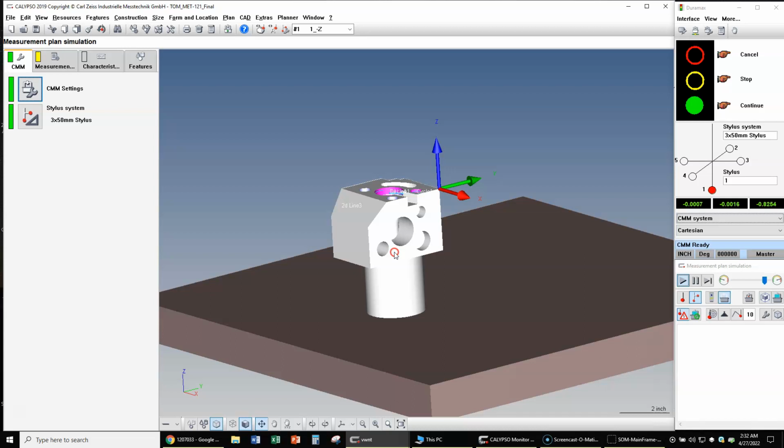Don't try to position it on the real machine. If you were writing this program offline on a computer, go ahead and position it. That's fine, because when you bring it over here, you'll do the manual alignment and it will correct it. But what you don't want to do is position it on the machine, because the machine will drive into itself. You don't want to override your manual alignment with some random CAD position.